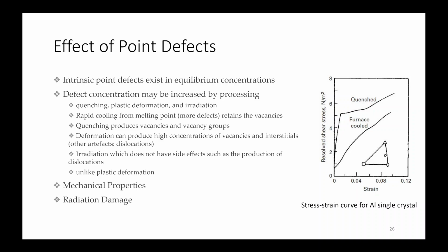Iron atoms have certain voids, and your carbon atom will go and sit in them. That is your interstitial defect. If iron itself is going and sitting at an interstitial site of itself, that will create a lot of lattice strain, so that requires a lot of energy, which is provided by irradiation.